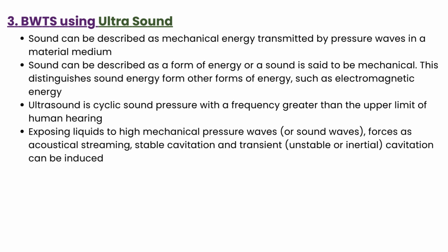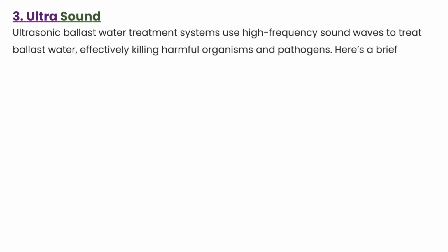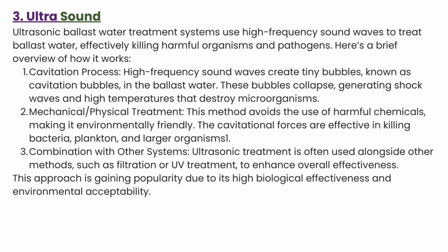Exposing liquid to high mechanical pressure waves or sound waves forces acoustic streaming, stable cavitation and transient, unstable or inertial cavitation can be induced. If we go further, an ultrasonic ballast water treatment system uses high frequency sound waves to treat ballast water, effectively killing harmful organisms and pathogens. Here is a brief overview.